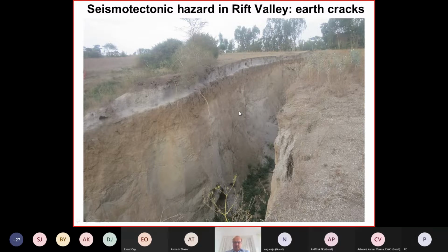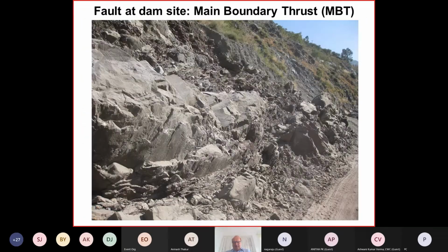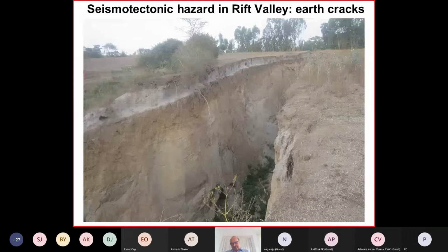It is here about 900 meters long. We walked along this fissure. And it is clear, if you have a dam built at such a location, it is impossible. Whereas in the previous one, where we have a trough, the material is still in contact, so you can build something. But if you have this situation, that suddenly a big fissure develops, and in Ethiopia, in this Rift Valley, they have quite a few of these.